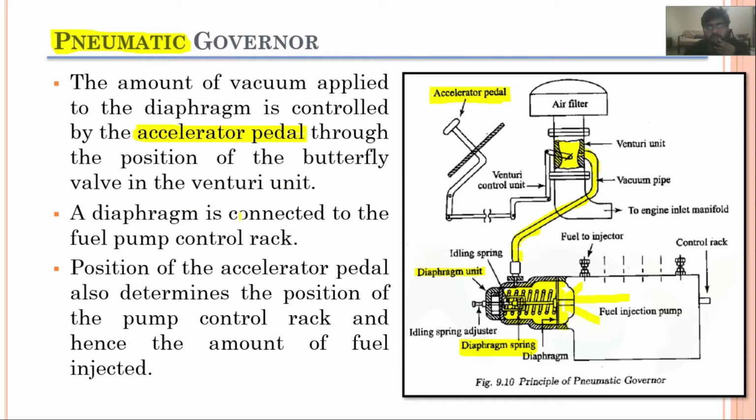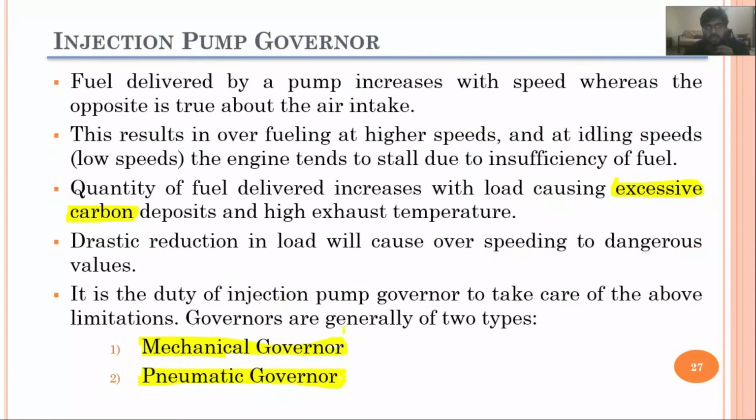This diaphragm is connected with the fuel pump control rack. The position of the accelerator pedal also determines the position of the pump control rack, and hence the amount of the fuel injected. So this is all about the pneumatic governors. Now in fact, this is all about the injection pump governors.